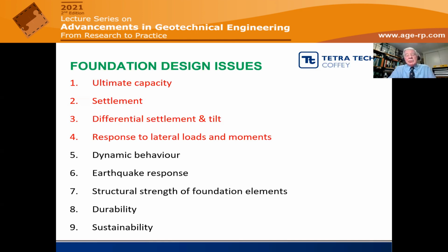We then need to look at the settlement and the differential settlement and the tilt of the foundation and make sure that they allow the structure that they're supporting to be serviceable. And we also need to be able to look at how the foundation responds to lateral loads and moments, because in many cases, these will be important, particularly for tall buildings, and we have to be able to cope with those.